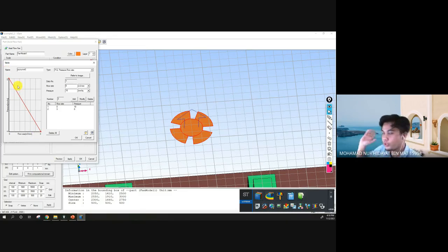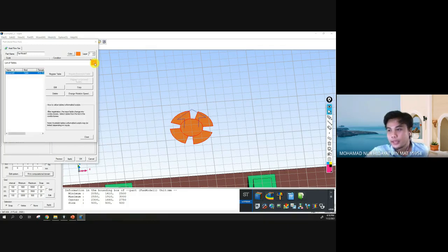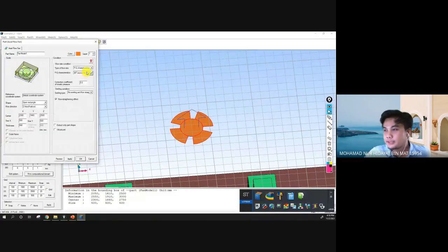Having different pressure will give you different flow rate. If you go to the manufacturer, you can ask, can I have the PQ characteristic for the fan? They will provide you. Normally, this PQ characteristic is applied to factories because factories may have different pressure. I'm not really sure about the fans in a normal classroom. You need to check whether it is a variable flow rate or a constant flow rate. Maybe for simplicity, we can use the constant flow rate.